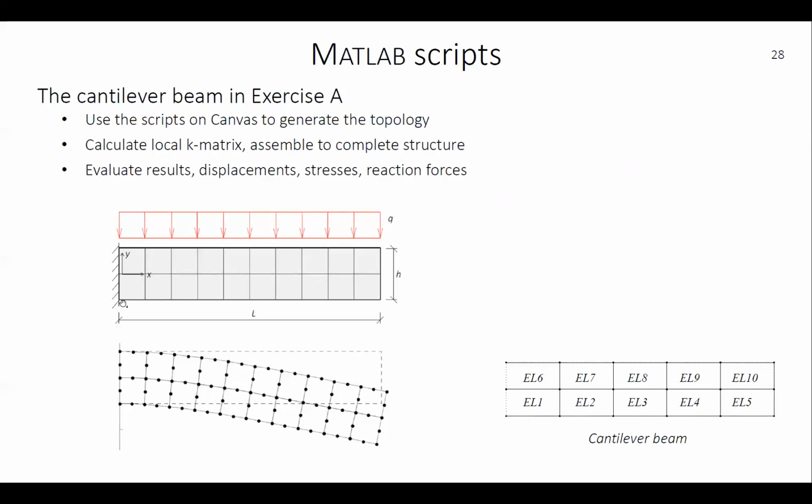Because plane elements only have translational degrees of freedom, you don't have any rotation and bending. But you will have a set of horizontal reaction forces, which can be defined as a bending moment along the center of the section.